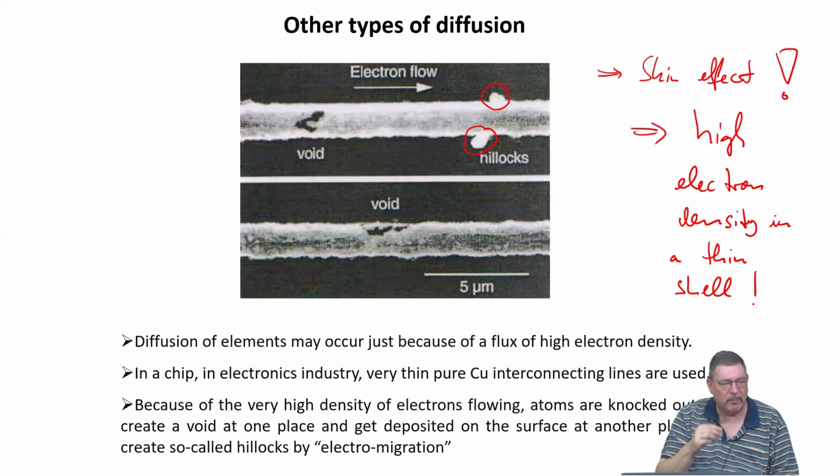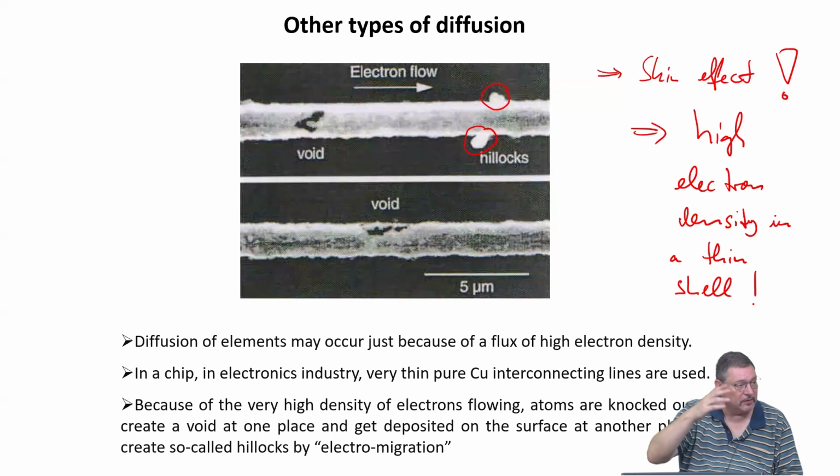And at some point, maybe there was a small crack or some imperfection in the wire, and there they aggregate, so they grow a new crystal, they find a new position, and this is then often causing mechanical instability, or maybe because of the electrical field and instability, you can get a short with neighboring wires or so.